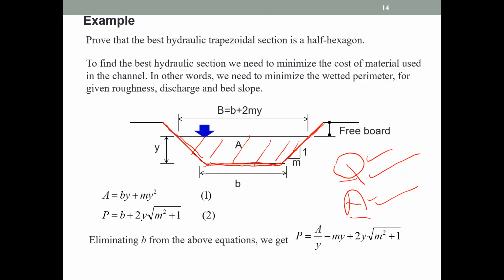Okay, so I will explain the basic idea. I need you to practice this derivation. All right, very important one. I need you to practice how to get it. Basically, for the trapezoidal section, the area is this one in terms of the width, the slope, and the y. y is the variable now. Now, we need to minimize the slope, not minimize, actually optimize it in a way that it will minimize our wetted perimeter while carrying this flow rate.